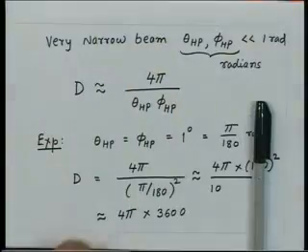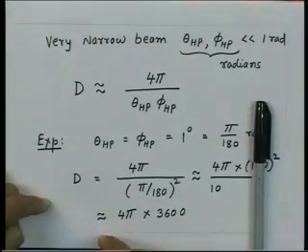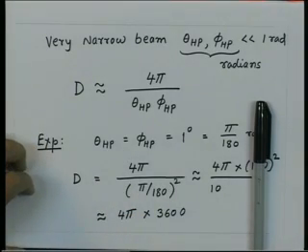So it is very important that when we talk about point-to-point communication like microwave link or satellite communication, we use antennas which are highly directive. That means their directivity is very, very large. By doing this, essentially we are reducing the power requirement of the communication link. So the antenna essentially provides a gain in power in a certain direction. Of course, this gain is not in the conventional sense like an amplifier, where the power is amplified; the antenna is a passive device.